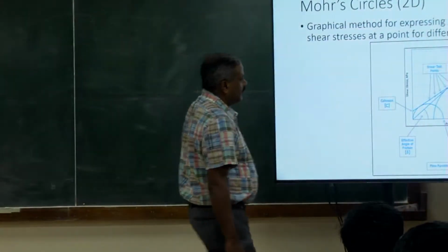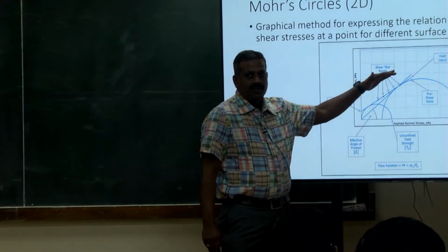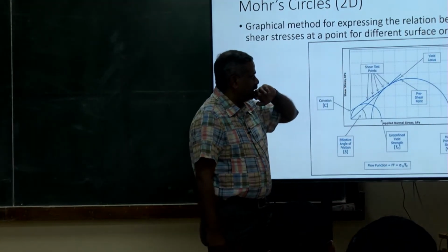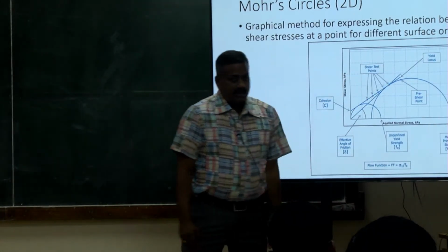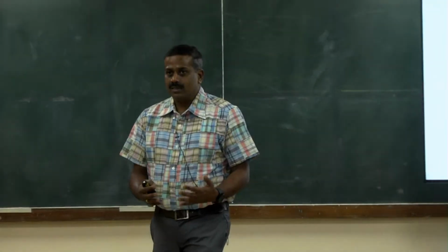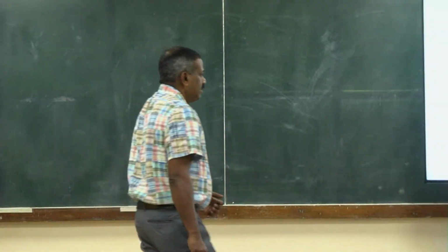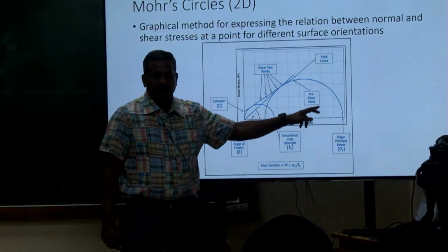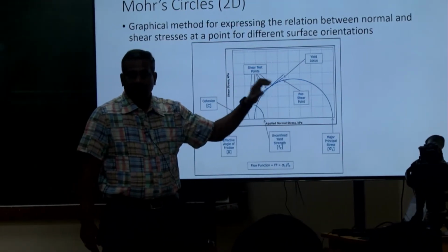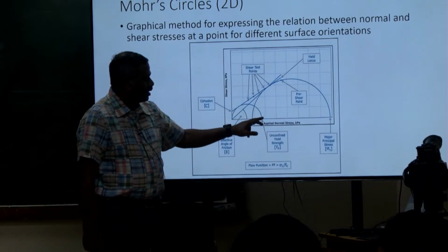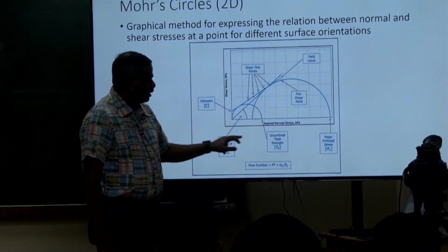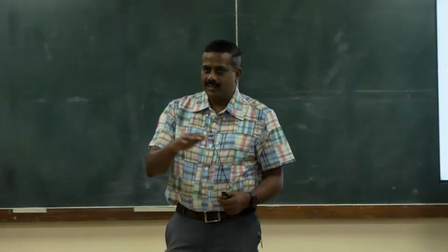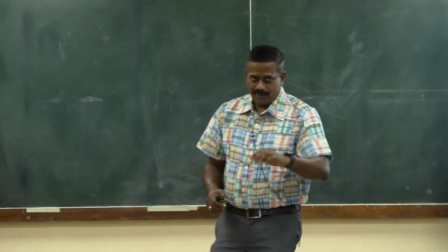Above this point, the powder will flow freely at these conditions. Again, we will go through some of those applications in a minute. When you get that point, you are not getting any meaningful information from those points. So using those points and the yield locus, we draw two more circles. You can draw more than two, but primarily we draw two more circles. I'm showing only half of this here. It will be a circle, but when we talk about powder flow, it's in 180 degrees, right? It's a plane, so we take half of the circle.